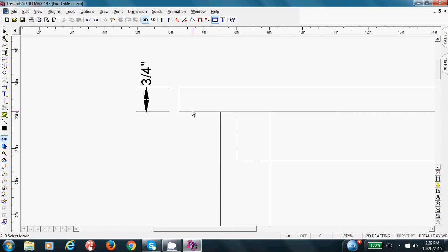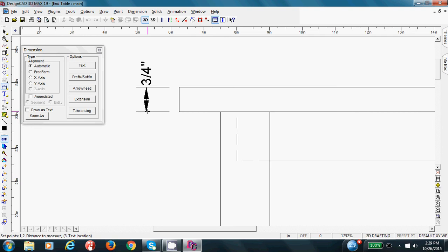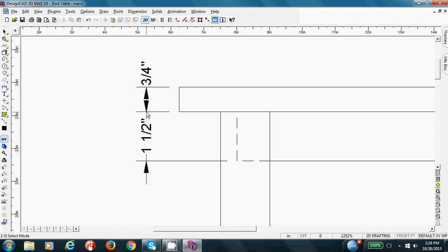When I dimension this, I want to take a dimension from this point, right click, to this point, right click, and I'm going to pull this out. And again, I'm going to just right click here. It's simpler than putting in a point relative. Now this gap is good, but I'm dimensioning through an object line, which is kind of a no-no. So right here, this is not good. It's giving me the 0.3 gap from my point here to here.